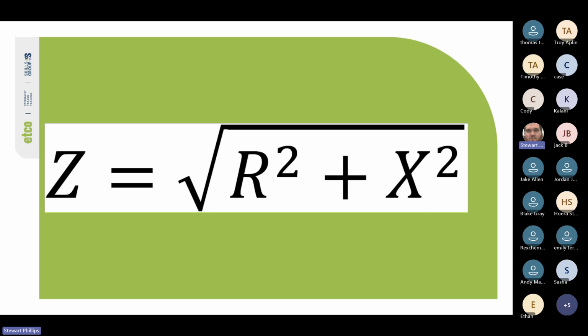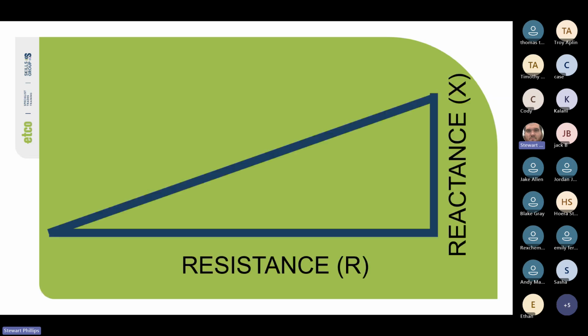While we draw reactance at 90 degrees to resistance in this model, that is the reason for the perpendicular relationship. So we have our hypotenuse there. The impedance is the total opposition to current flow, combining both resistance and reactance. But again, they interact with the current flow in different ways, so we can't just add them together. So we use this when we do the mathematical equation.